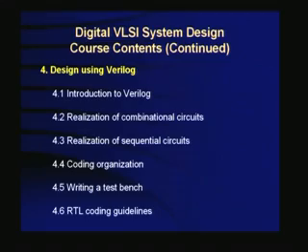You cannot fabricate it every time. So you have to write what is known as a test bench. And when the test bench works, it will work with your design finally. And then RTL coding guidelines will be given to you. Only certain things are synthesizable.